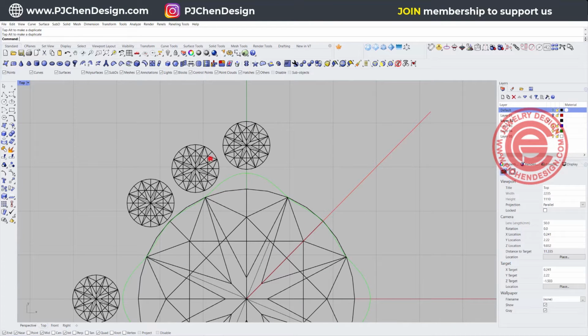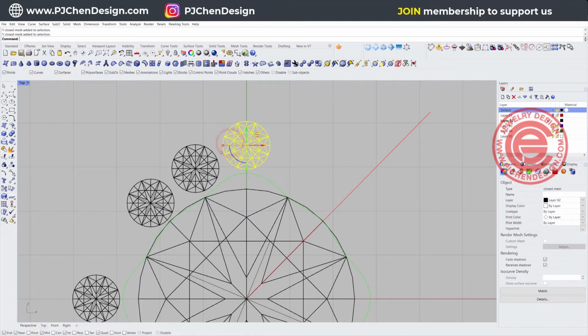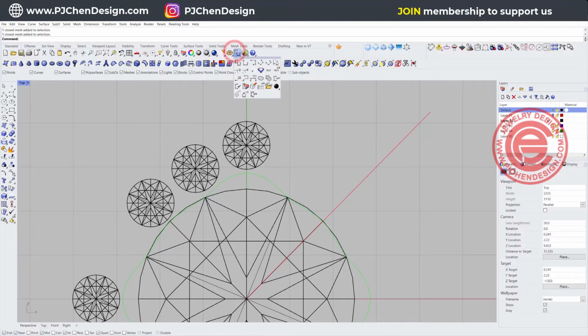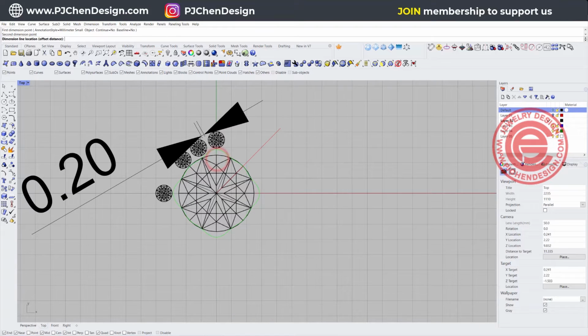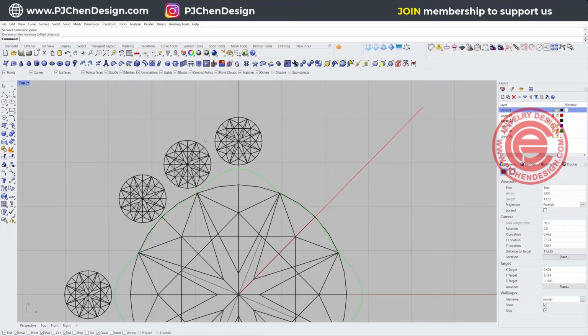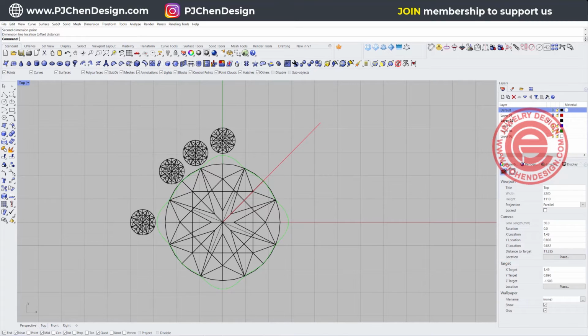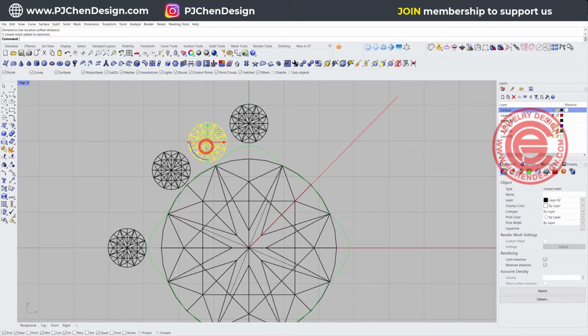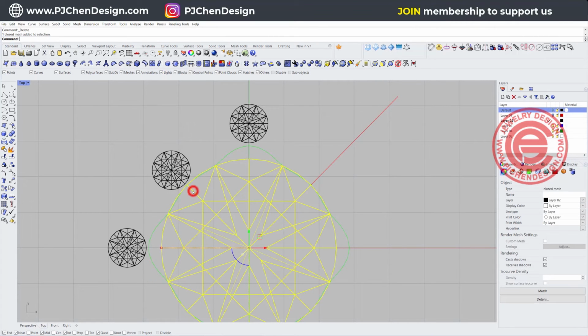You just want to make sure that the stone is not way too far. In this case, if you use the measurement tool, you're going to measure in between roughly here and here, and that gives you 0.2 millimeter, which is a good size because we need to have the prong there. Okay, if that looks okay to you, we need to make them more accurate. I'm going to draw a line starting from this point. Make sure that I hit the Tab key, and then when I move it out, it will come out as an extension right there.